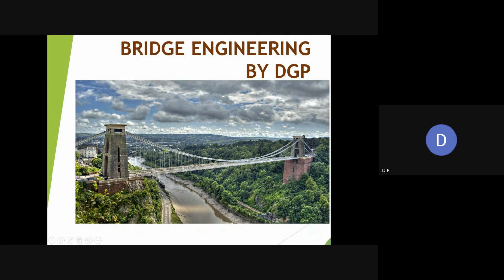So this particular tendon is connected to the two pylons on the edge of the river, and the vertical strands are connected to this particular big tendon, which is in the form of a sagging curve, we can say. And particularly this deck is supported by these vertical strands. So this is suspended. These strands are suspended from these larger tendons, or we can say ropes.